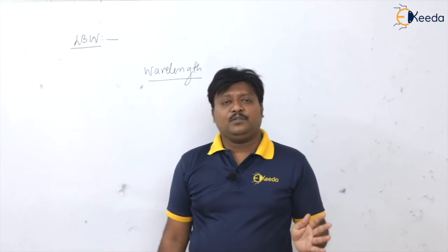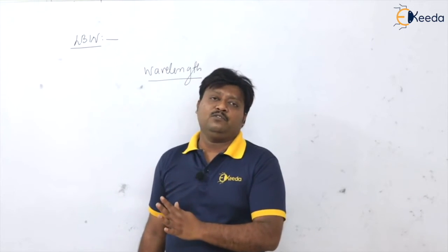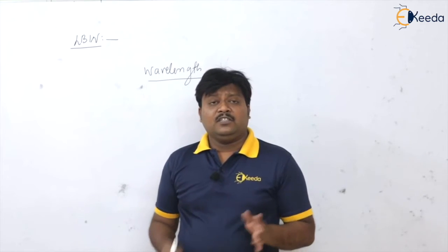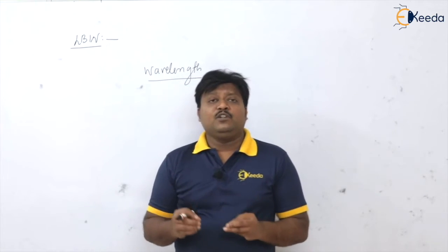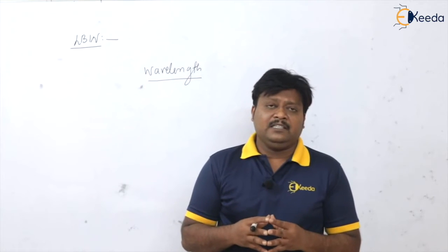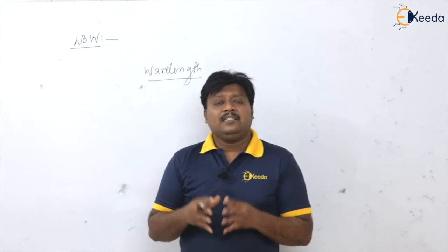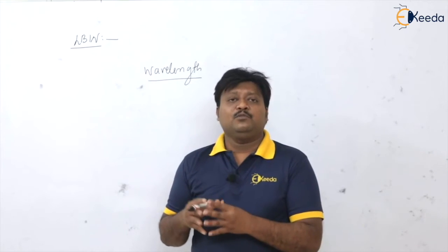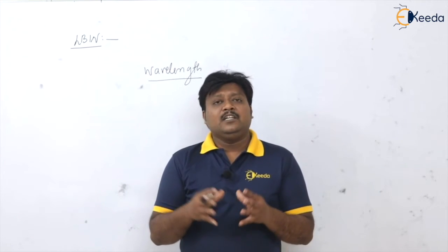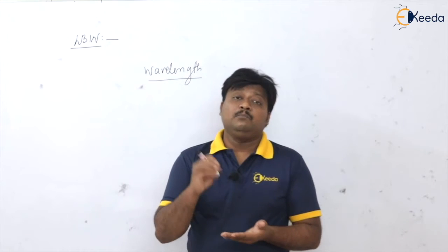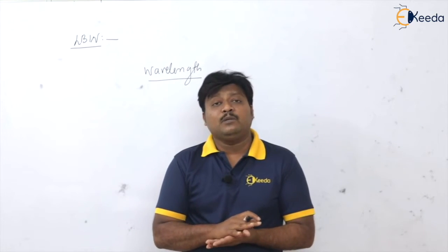So in machining operation, the usable wavelength is from 0.4 to 0.6 microns. Here, the wavelength is selected such that it produces heating of the workpiece only, so that only melting takes place but no vaporization.